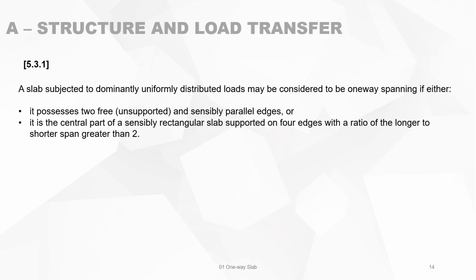So if one dimension of a rectangular slab is more than 2 times the other dimension, then we can treat this slab as a one-way slab.